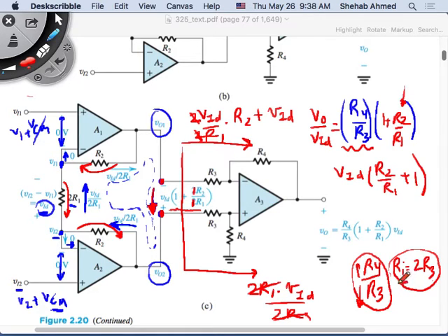The instrumentation amplifier in the previous case, with the ground connection, already solved this. This one solved the second problem. So the previous one with the ground connected here already solved this input impedance issue, because we did the gain here. We controlled the gain of the signal at the front end using the non-inverting amplifiers, and then we made the difference amplifier low gain. If I make it low gain, meaning R4 can be low and R3 can be high, which means the input impedance will be high. So I can have a high input impedance for my difference amplifier.